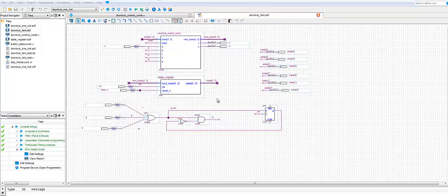Don't forget to include your finite state machine circuitry here for A. We did the finite state machine controller for A in class, and so basically we have our little controller to just output an A, so that we only see an input once per clock cycle, or it only lasts for 1 clock cycle. So once we have that, we have our finite state machine BDF. We can go ahead and run ModelSim on this particular project.